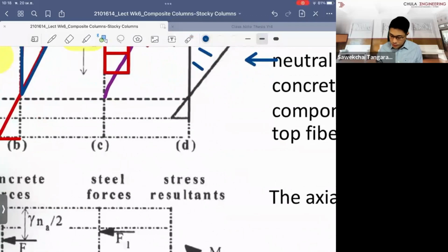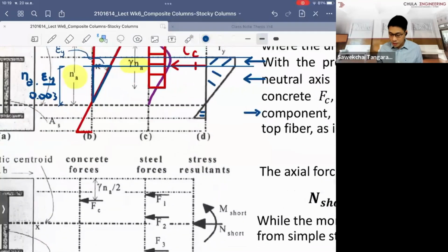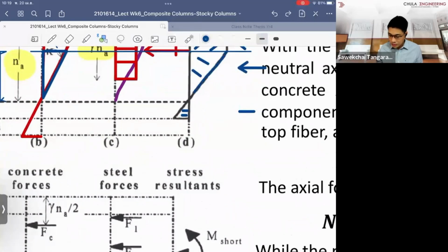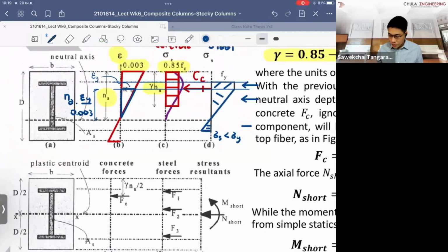And in the bottom, you will have the tension based on the stress coming from the triangle stress diagram. Everything you just stick to the linear line of the stress. So at the bottom may not reach the yield stress, right? So the stress at the bottom in the steel is still less than the yield stress in this case, right? So we keep doing this.